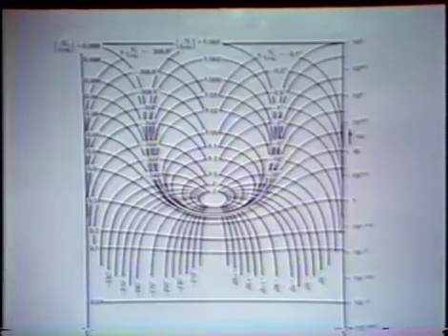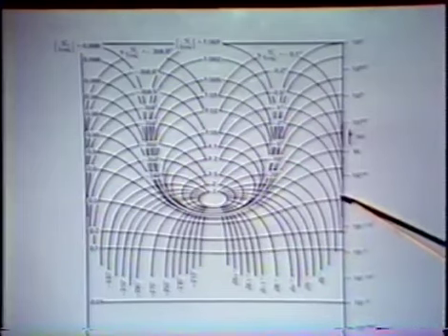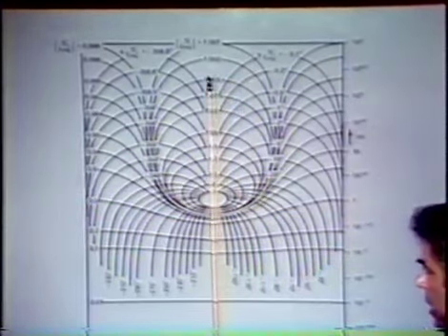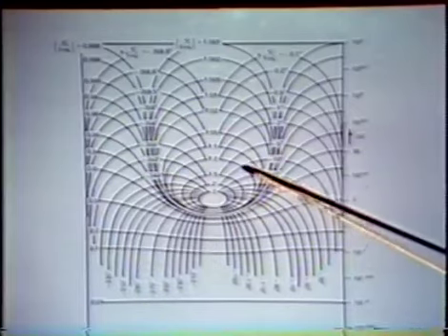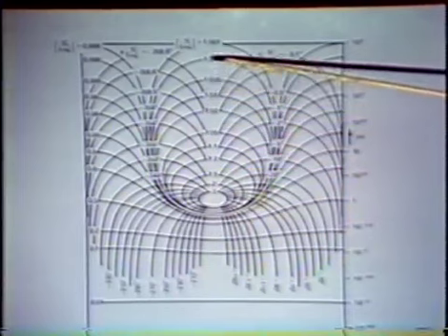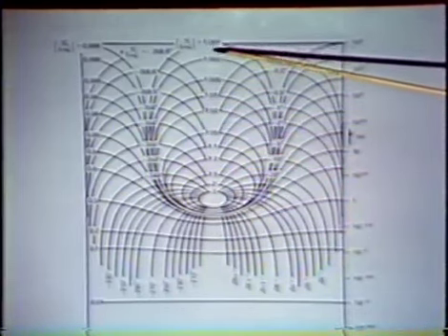In the Nichols chart, the critical point is, of course, the minus 1 point, a magnitude of 1 and an angle of minus 180 degrees. And what happens as we approach that point? Here's a magnitude of 1. Here's an angle of minus 180 degrees. And as we approach that point, the magnitude contours get larger and larger and larger. Here we're starting at a magnitude just slightly above 1.